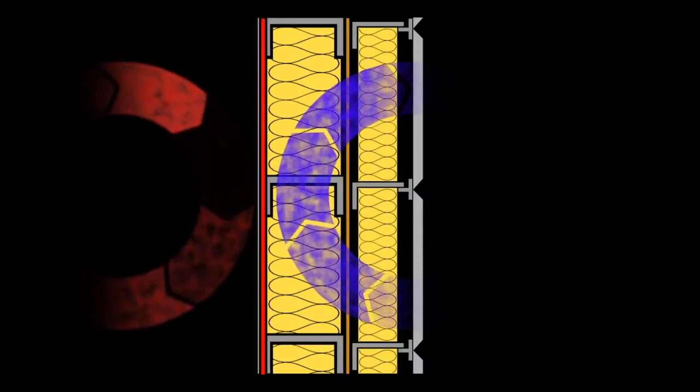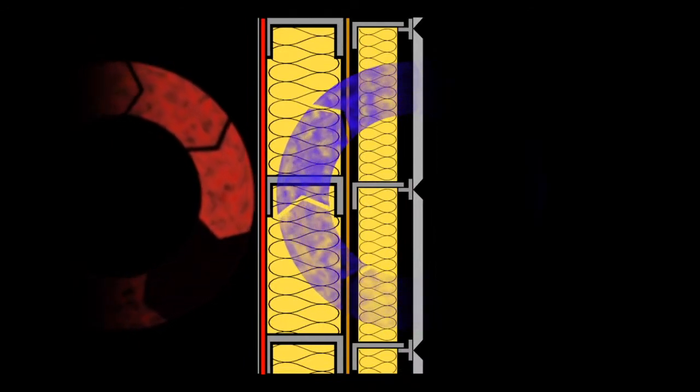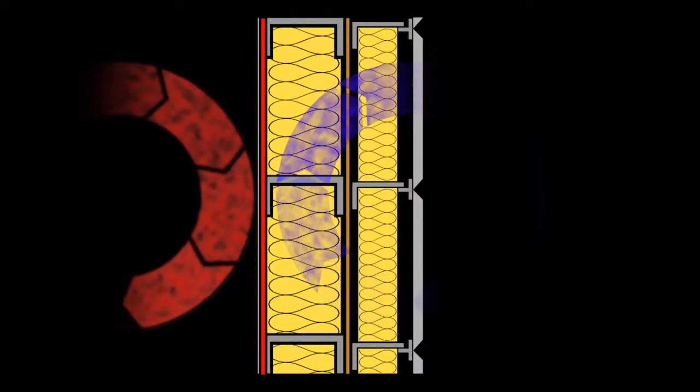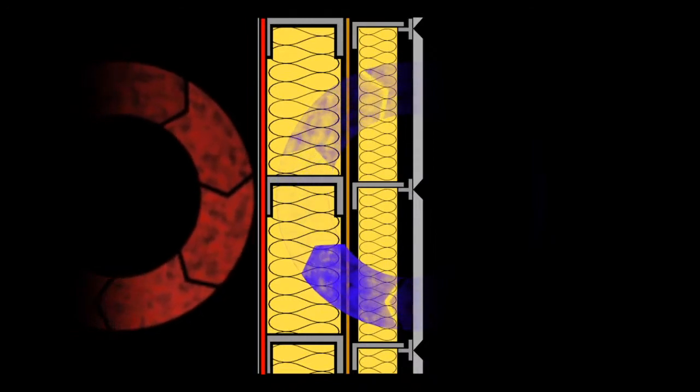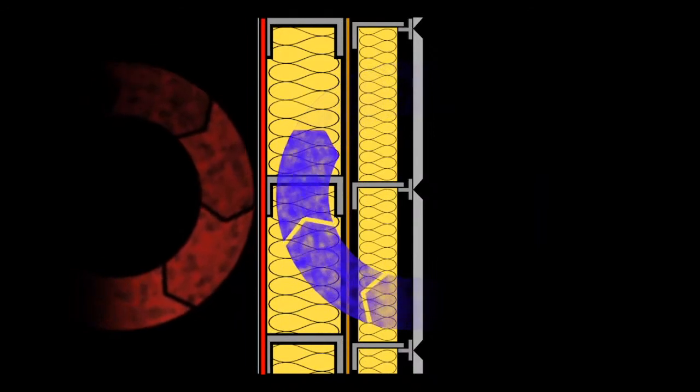If care is not taken to seal all external elements effectively, this can also allow cold air movement around insulation, known as thermal bypass or wind washing, which can lead to reduced energy performance, cold spots and condensation issues, particularly if there are continuity issues with the airtight VCL line.